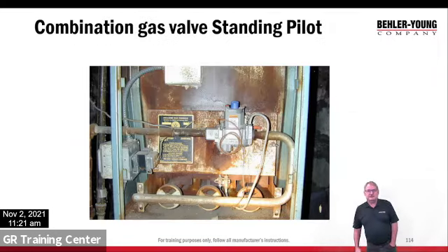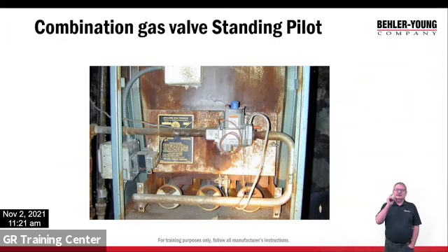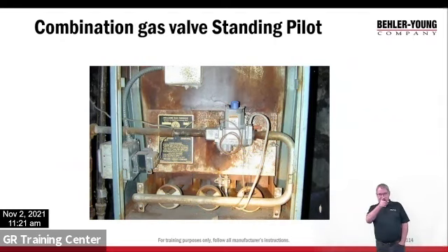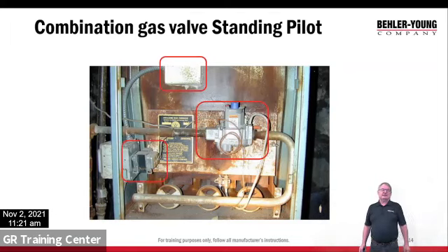So there we go. This is an old style furnace. You can see the old burners with the air shutters for adjustment. The burners go into the heat exchanger. You see down at the bottom, the standing pilot. You see the thermocouple going back to the main valve. You see the transformer off to the left there. There's the valve, there's the fan limit control, there's a transformer.